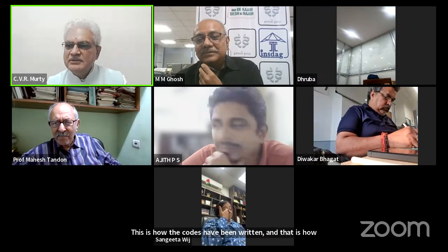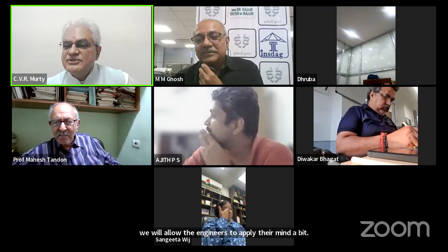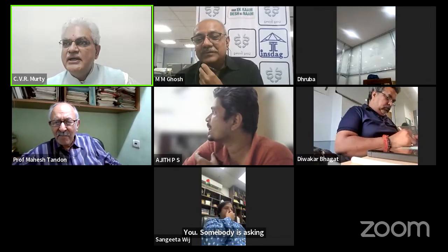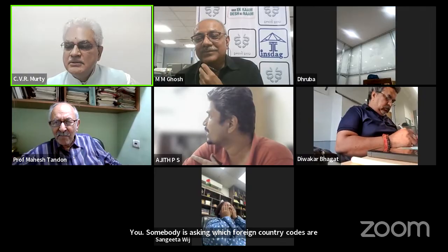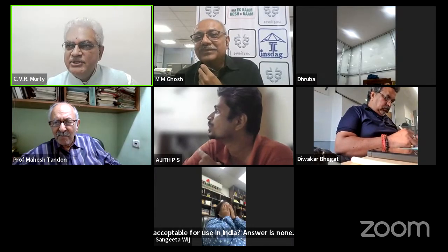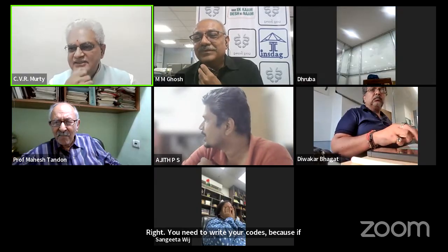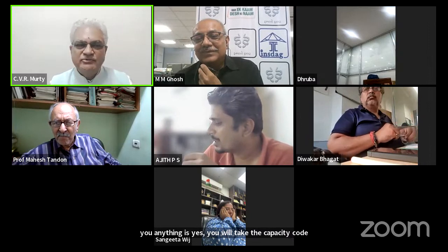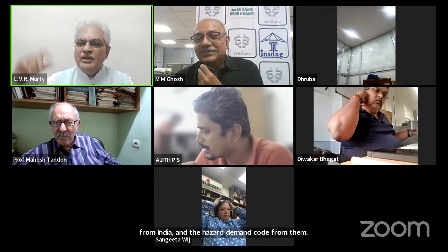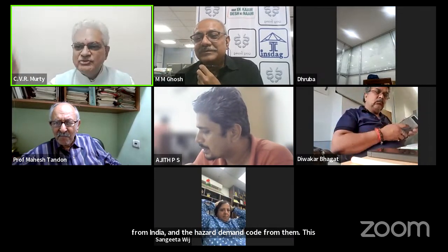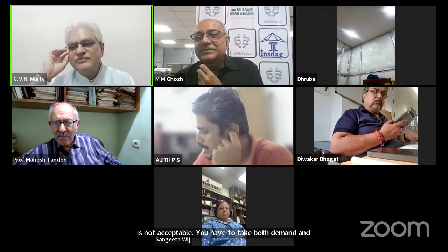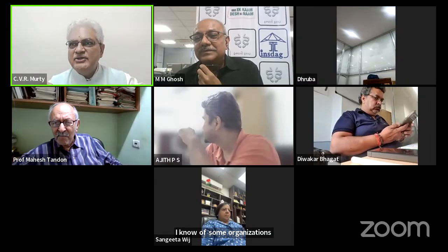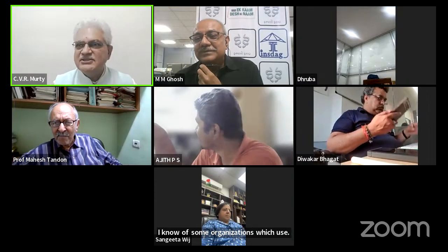Right? Now, somebody is asking the question, which foreign country codes are acceptable for use in India? Answer is none. Right? You need to write your codes, because if I tell you anything is yes, you will take the capacity code from India and the hazard code, demand code, from there. This is not acceptable. You have to take both demand and capacity code from the same country. I know of some organizations which use other country codes, both demand and capacity, and build structures in India.